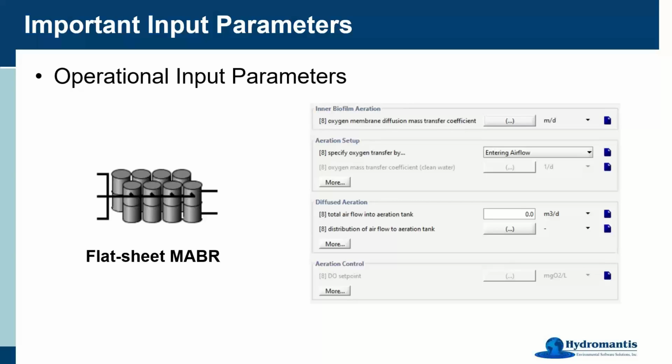This can be something you could control, and I've seen situations where this has been used in concert with one of our timer controllers so that it will allow for alternating aeration. Sometimes the air is on, sometimes it's off, and by doing that here, you can alternate this between 0 and some other value. That's a really sophisticated way to do some interesting process control here.